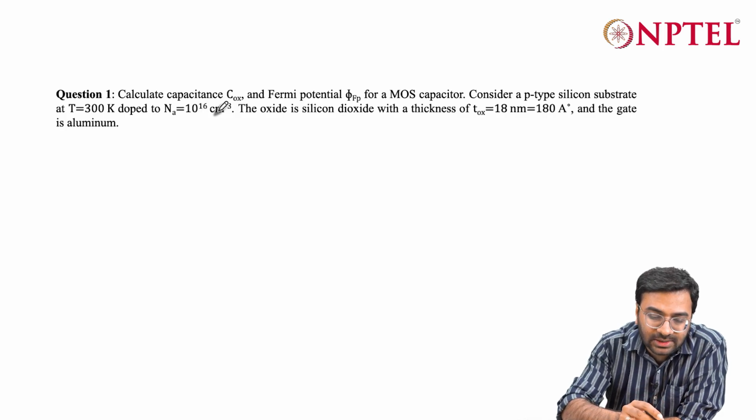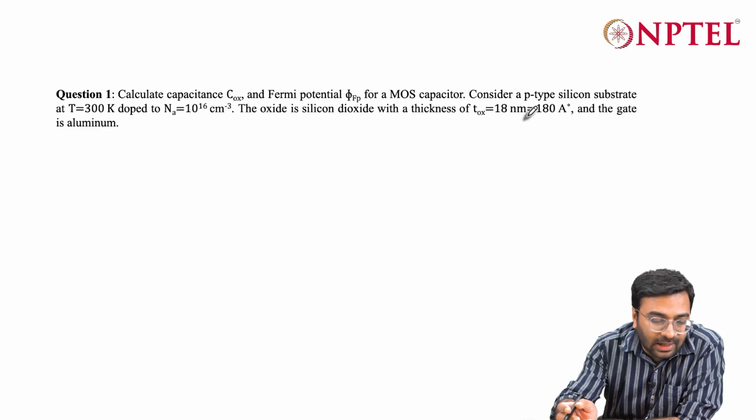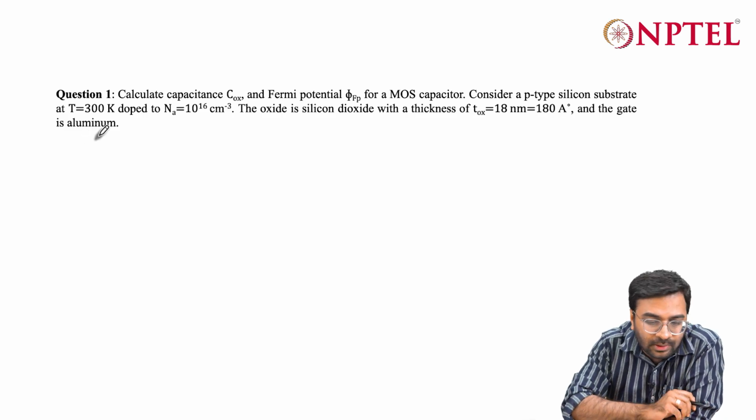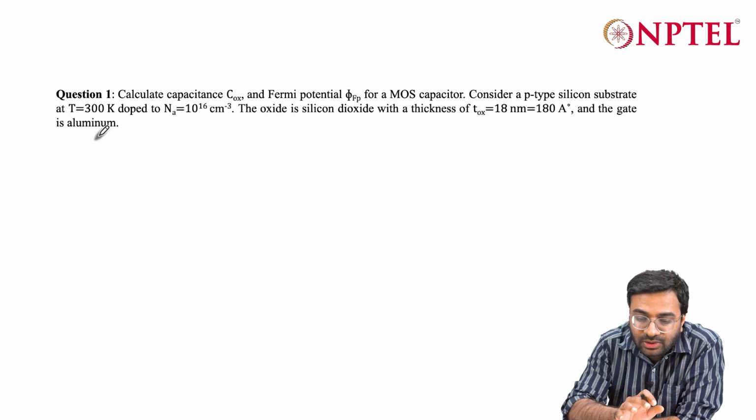The oxide is silicon dioxide with a thickness Tox of 18 nanometer, which is 180 angstrom, and the gate is aluminum.